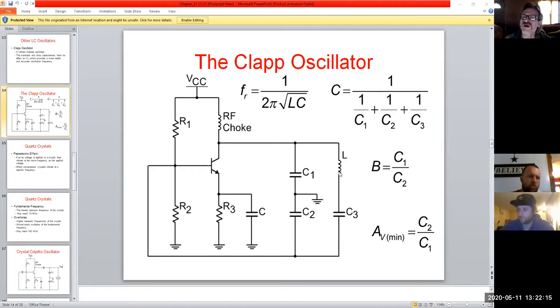Because if we went one way with this, let's say we went more inductance, what does that do for us? Well, then that means our current is going to lag behind our voltage. Now, if we go with the capacitor effect, right? Capacitors don't like voltage changes. But when we apply the two together, you try to balance that out. And that's why you come up with a circuit like this, right? So we try to reach what they call frequency resonance.